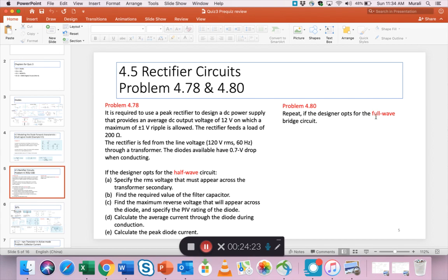But if you have a full wave rectifier, then you can have a smaller size capacitor. Of course, now you're spending money on many diodes, but sometimes it's easier to buy more diodes than it is to buy a big capacitor. And big capacitors need a lot of space. They have other problems. So that's why the bridge rectifier, full wave rectifiers are preferred.